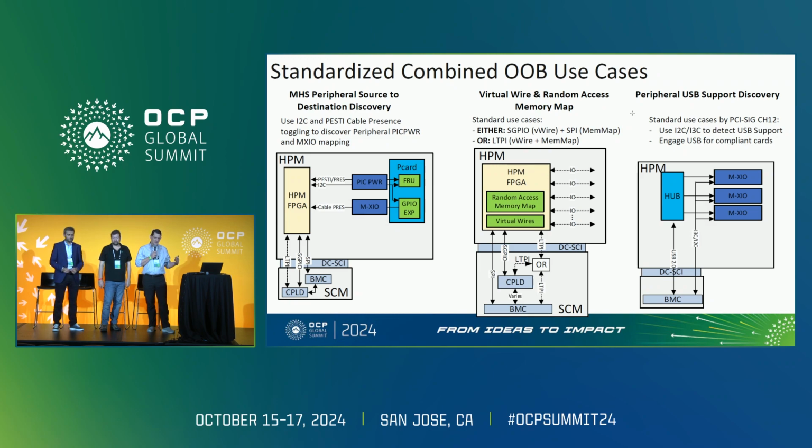It goes into these FlexIO rules, which are in the released PCI base spec, that talk about how the different situations of break before make work when you're negotiating the functions that go across a connector, like a PCI CEM connector that already had legacy functions on the pins. For example, on the PCI CEM, the JTAG pins were rarely used through a bunch of surveys, mostly in a manufacturing situation, so they were kind of wasted in real time. That was a situation where we were able to flex in the USB interface without breaking backward compatibility.